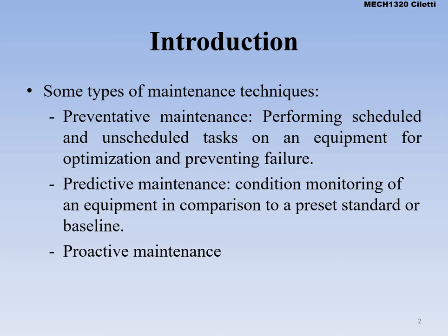Proactive maintenance is making things on time, checking equipment as we should be, so that when it says you need to take a look at an engine after it has run a certain amount of time, you're constantly taking care of that. You're checking a chain to make sure there are no nicks, burrs, or dents. You're always checking fluid levels, just like you'd check the oil in the engine of your vehicle.